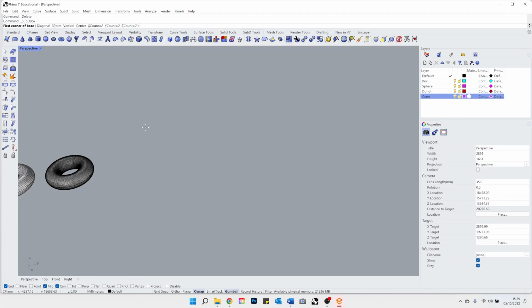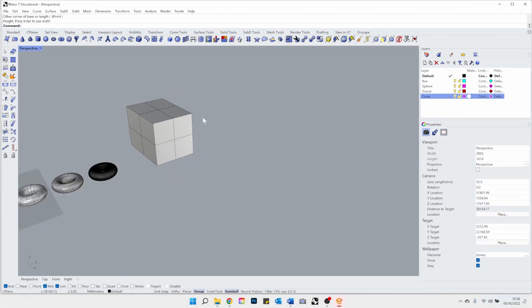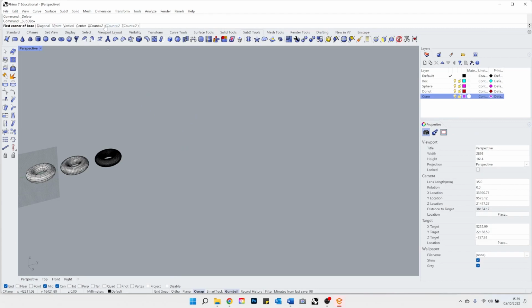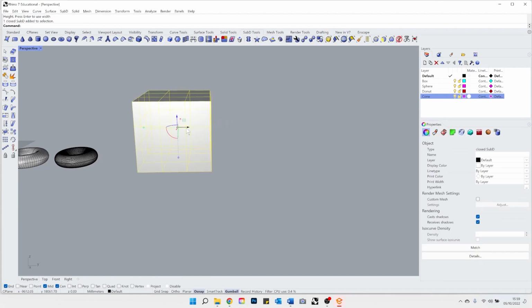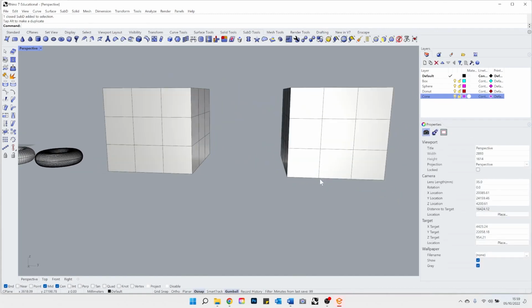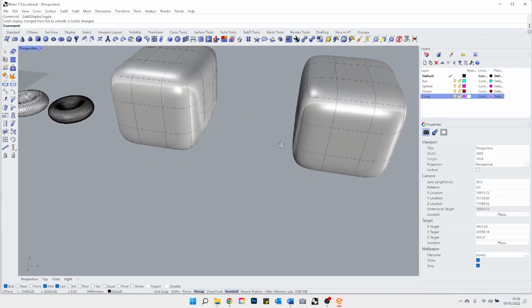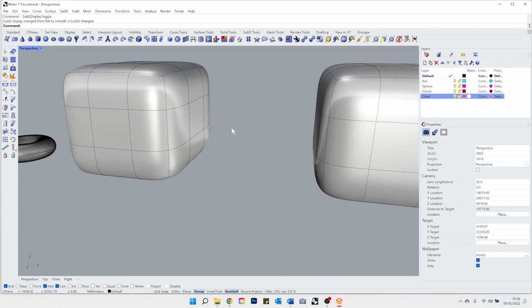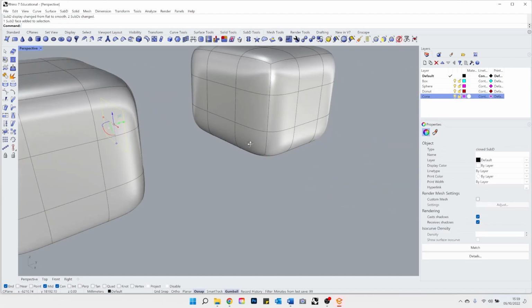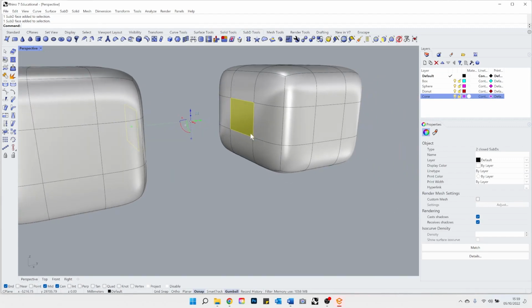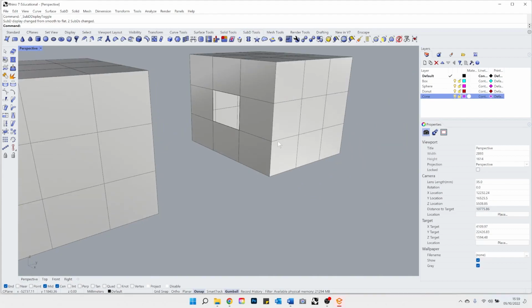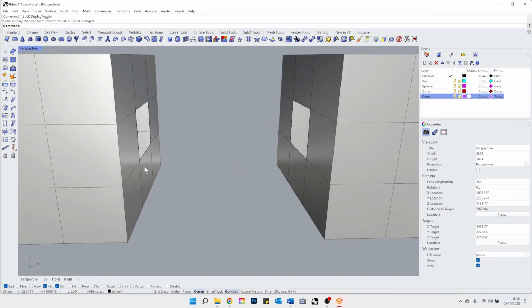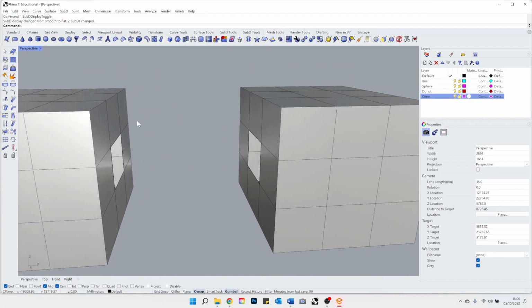So the idea is, for example, if I create a cube, which is going to be a sub-D, and I change its wireframe into, for example, 3, 3, and 3. You have two simple cubes, but if you click Tab on your keyboard, it's going to smooth your object out. And you can start working specifically with edges, polygons, and vertices. By holding Shift and Control, you can select polygons in between, and you can delete them. And if I click Tab on my keyboard, you can see how it looks rigid, more simplified. And you can bridge those two objects in between.